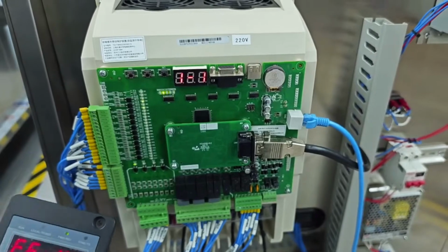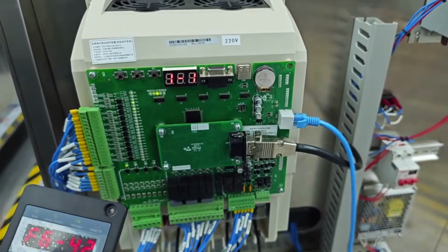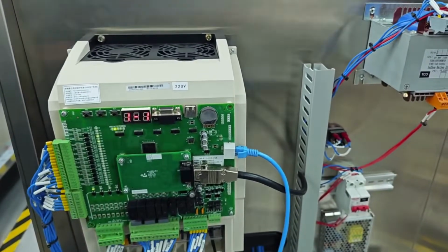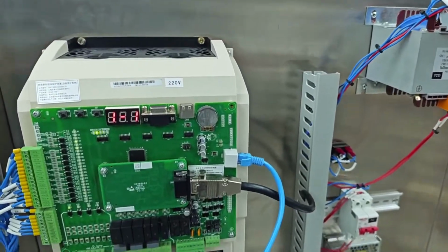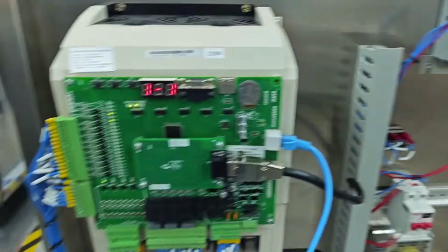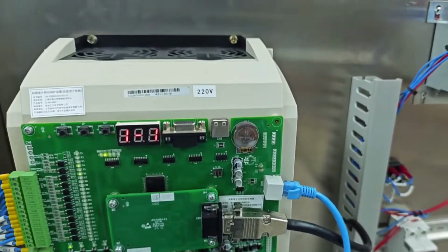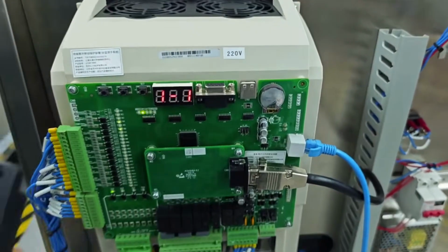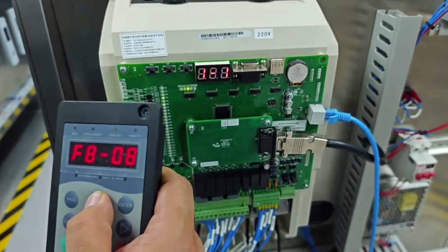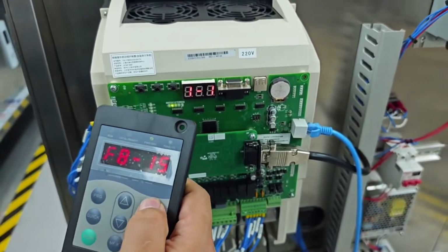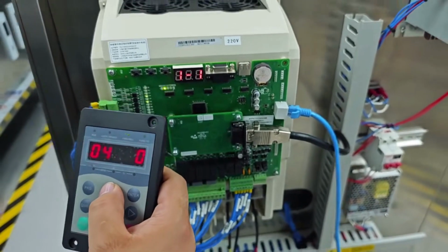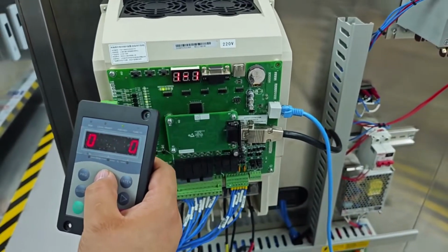FE32 bit 3 equals 0 disables early door opening. FE32 bit 2 equals 0 disables releveling. F611 bit 13 equals 1 enables E534 self reset. If the car door is forced open, the system will attempt 3 door cycles. Persistence of the fault triggers fault 53.